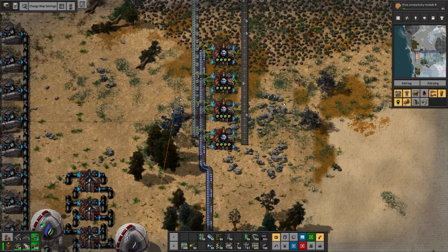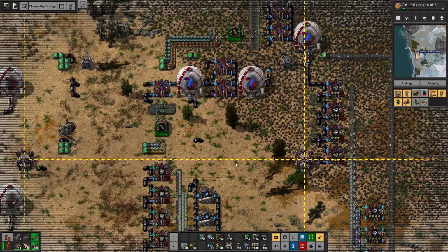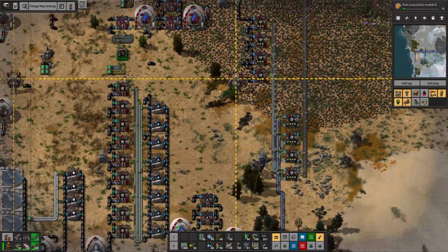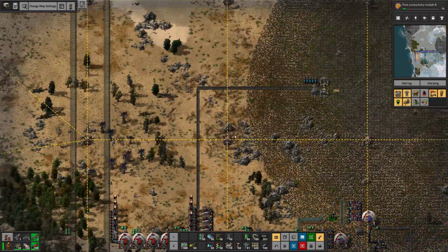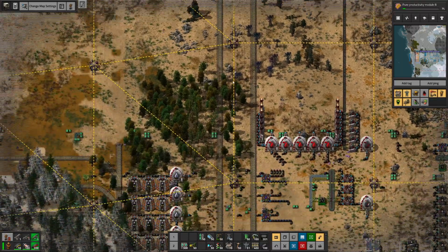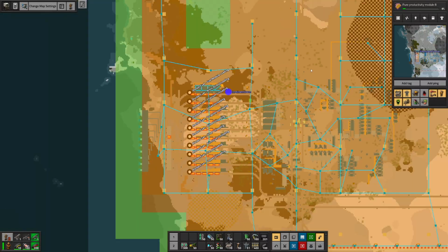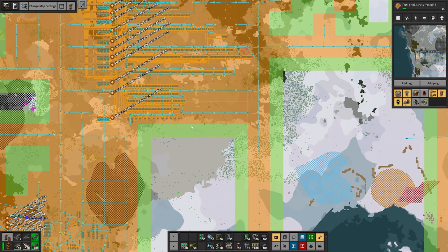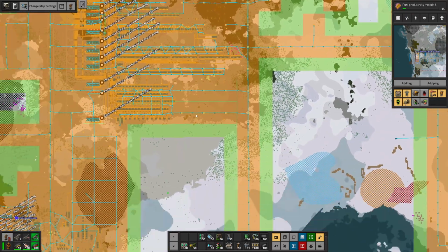And it's a rocket that can be turned on and off real fast. It can also relight pretty much infinitely. A lot of advantages to hypergolic propellants. The big disadvantage to hypergolic propellants is they are horribly toxic. And their reactant products are also very nasty as well. And they're fairly dirty to make.